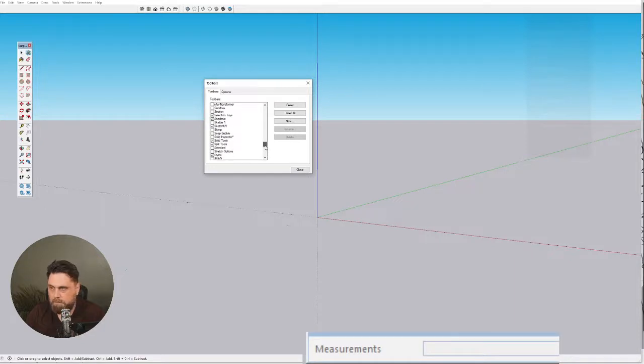and look for the, I think it's under L. It's called the large tool set. So let's turn on the large tool set. And I think there's another one called the Getting Started tool set that you can turn off if you want, because they are going to be redundant. There's really nothing in the Getting Started toolbar that isn't in the large tool set as well. So you can just use one or the other, but you don't necessarily need to have them both on at the same time. So turn on the large tool set and then turn off the Getting Started.